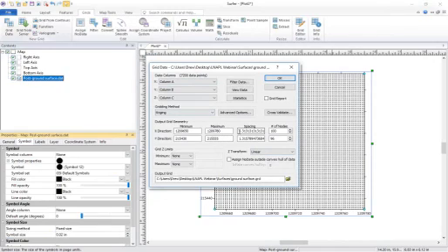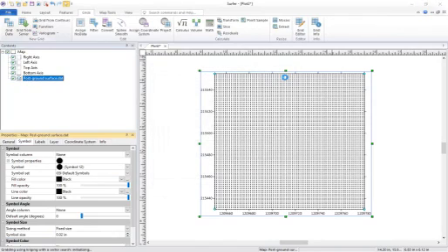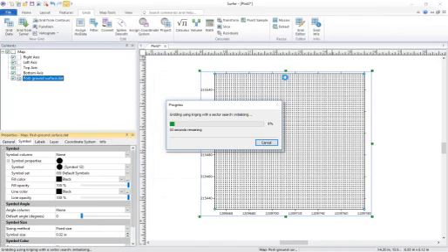And I'm going to adjust the spacing just a little bit here in both of the X and Y directions. I'm going to make sure that the assign NoData outside convex hull option is unchecked. And our output grid file looks good. So everything looks good in our Grid Data dialog. I'm going to go ahead and click OK to grid the data. And it's going to take just a second, as you can see, that progress indicator right there on the screen.